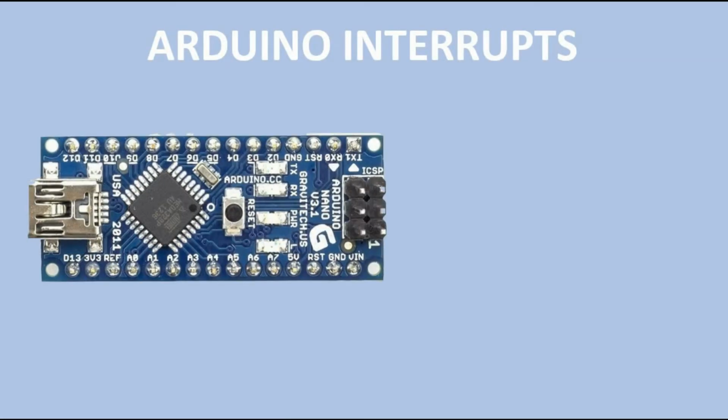How do Arduino interrupts work? They occur in response to an external event, such as an external interrupt pin going high or low. When such an event happens, the processor takes immediate notice, pauses the currently run code and saves its execution state, runs a small chunk of code called interrupt service routine, ISR in short, and then returns back to whatever it was doing before.